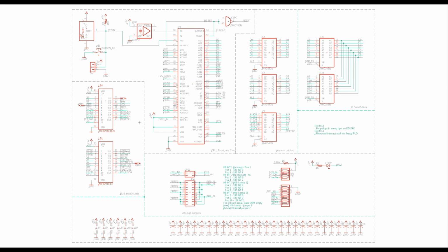Okay, here are the schematics for the H8 8186 board. There are about 6 pages to this, so I'm not going to go into it in a lot of detail. It is very similar to the SBC-188 from RetroBrew, as I mentioned before, with the obvious changes necessary for it to be a 16-bit data bus rather than 8. So our 8186 CPU is sitting here in the middle, and it's got a clock oscillator currently at 16 megahertz. It divides that in half, so this would be for an 8 megahertz CPU. For the 25 megahertz CPU I have out there, I'm using a 50 megahertz oscillator.